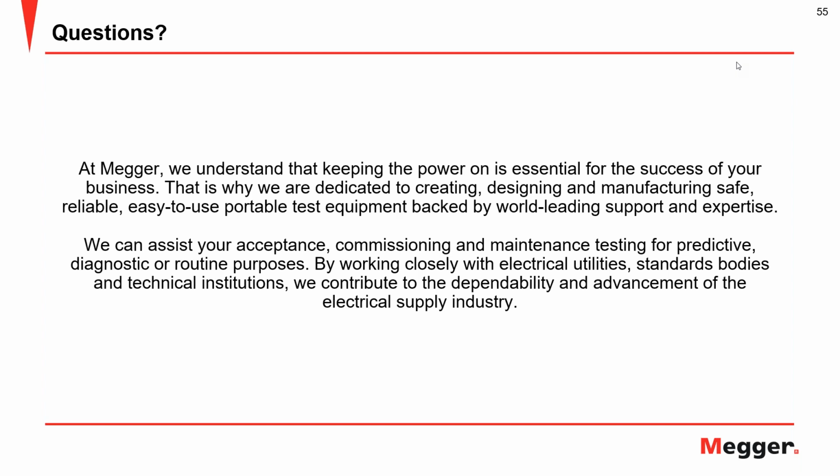That is different than in the TDR measurement where I induce a pulse. In the PD measurement, I don't induce any pulse and measure it. The pulse is induced by the defect in the cable, so I cannot get a measurement before the event occurs.